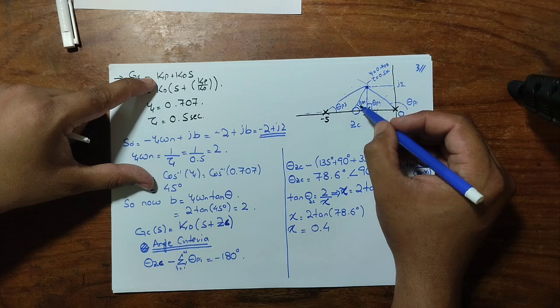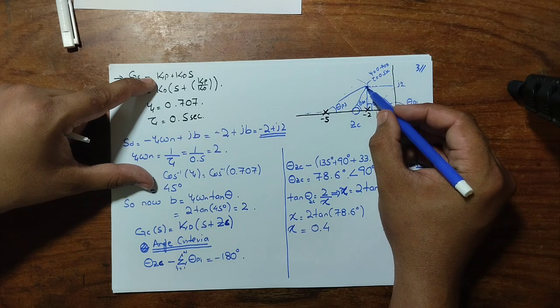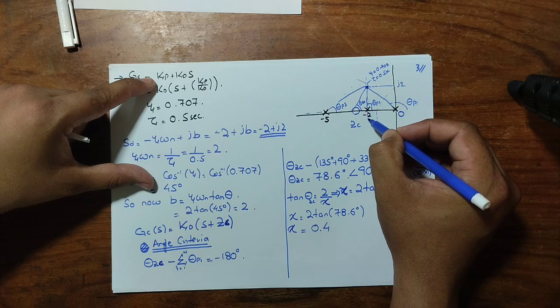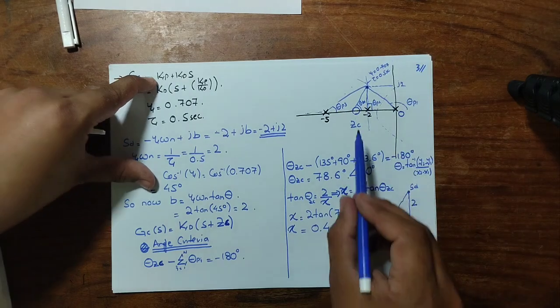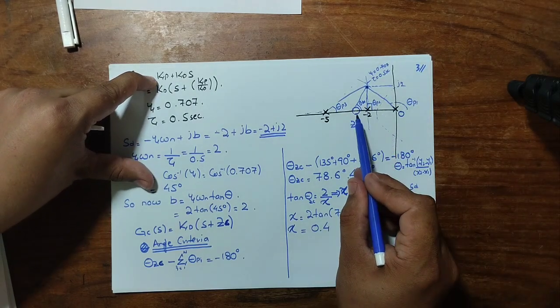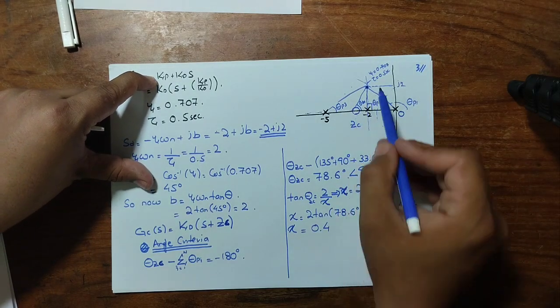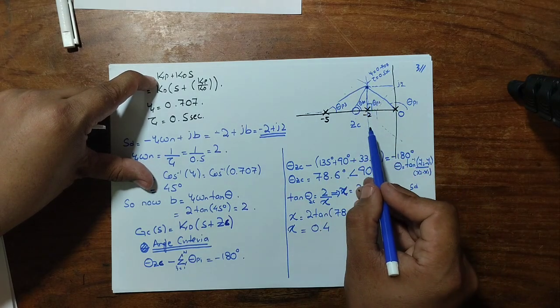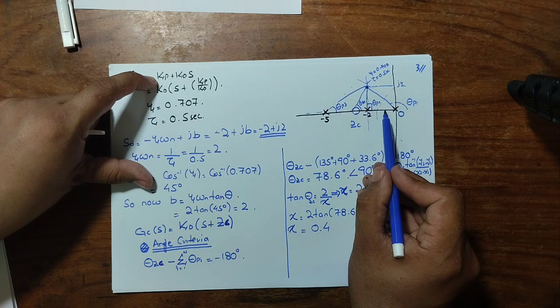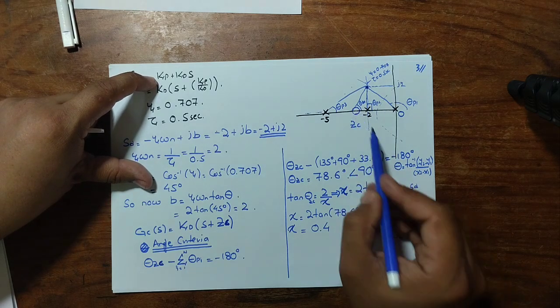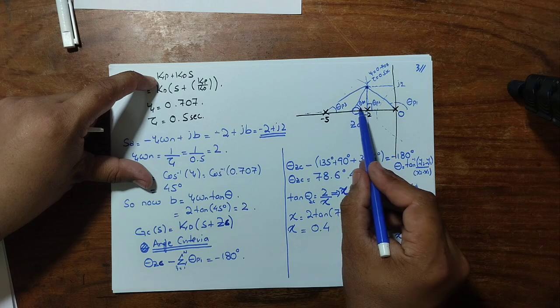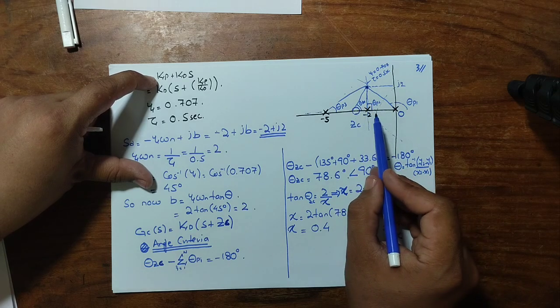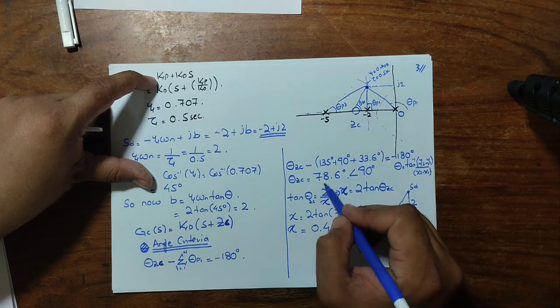But this desired point is less than 90 degrees, so we have to place it compared to this axis, the perpendicular line that will cut the real axis for this desired point. We have to place the zero either on the left or the right of this perpendicular line. Based upon the value of the angle that we obtained, we are now in a position to place it on one of these two sides. So the obvious choice is the left side.